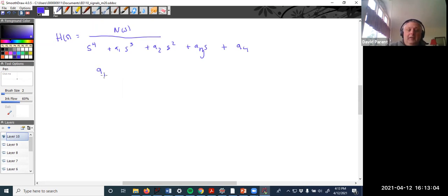A1, all the A's must be greater than 0, right? Because if any one of these is 0, you've got a missing term, and they all must be positive, right? However, there's more conditions to make it in control. So if all the A's were 1, you could have a pole on the right-hand side, or you'll have an oscillator or something.